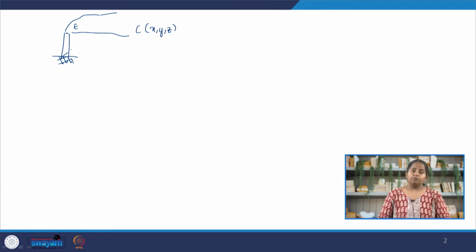Then the other thing we want to look at is the size and the weight of the contaminant. If the contaminant is big enough or heavy enough to settle down closer to the earth, then the plume will naturally gravitate towards the earth's surface. The next thing we need to look at is how the air will spread. Now, the spread of the contaminant once it is released from the chimney will depend upon two things. One is the transportation by wind.